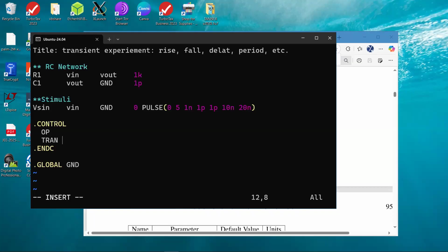This is more important when we deal with convergence and all that. Just keep it 40 picoseconds, okay? Or you can do 10 picoseconds, and 10 picoseconds and 40 nanoseconds is what we are going to simulate it for. Everyone's got it? So just get this going and we'll simulate first, plot and make sure it looks right, and then we'll try to measure it.